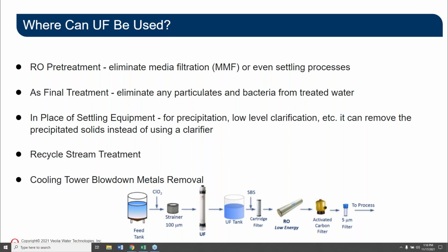As I've mentioned before, it's used a lot in the food industry, from everything from concentrating proteins to clarifying fruit juices. We also use it for pathogen removal in both the food and the pharmaceutical industry and the water streams. It's used in even chemical separation processes as processing ROs. Certain types of ROs are very good at separating oil and water emulsions and are used readily in recycling wastewater for reuse in many projects.